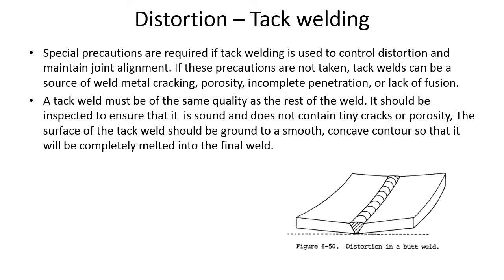So you really need to put emphasis on getting that root, and any tacks that might be incorporated into the root passes, that's got to be solid. That's got to be really good quality, because otherwise you're going to chase that all the way to the top of the weld. Sorry, kind of got off on a rant there, but trying to tie a bunch of things together here.